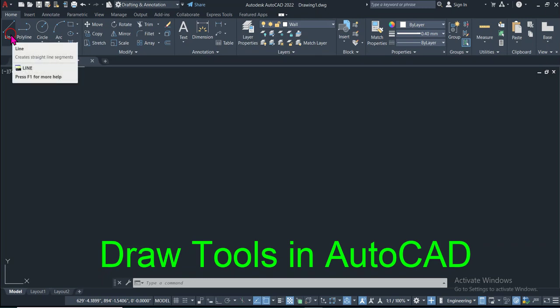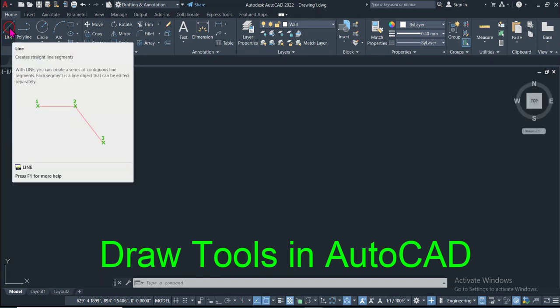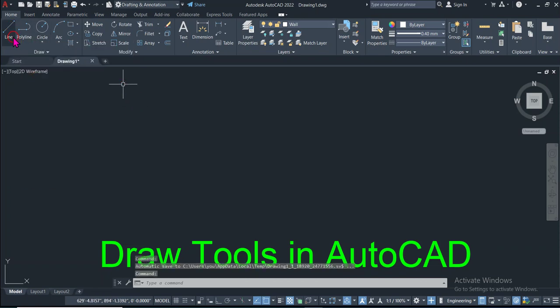With the help of the line tool, you can draw any type of line in the AutoCAD workspace depending on your requirements. If you want to draw a line, you will click on the line tool, and then as you can see in the command line in the AutoCAD workspace, it requires you to specify the first point. Arbitrarily I'm clicking here, so this is the first point. Now you can see in the command line it requires you to specify the next point.